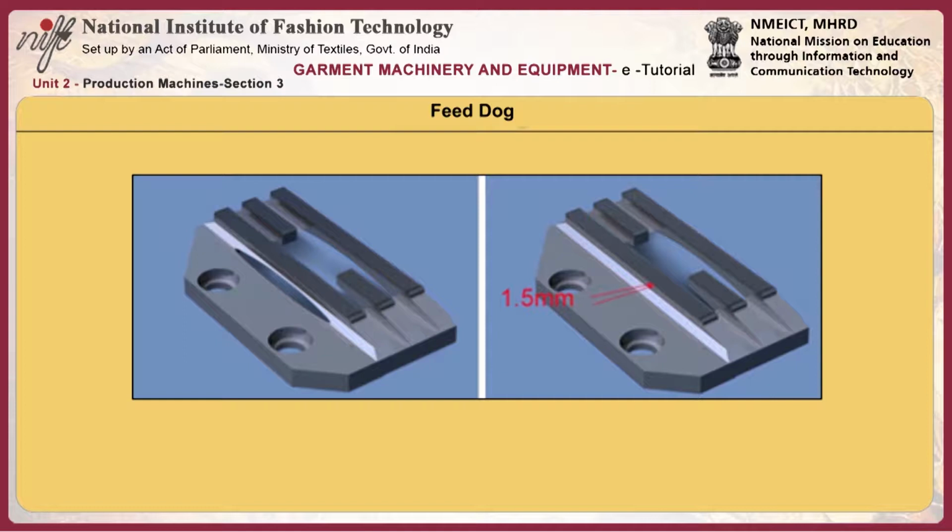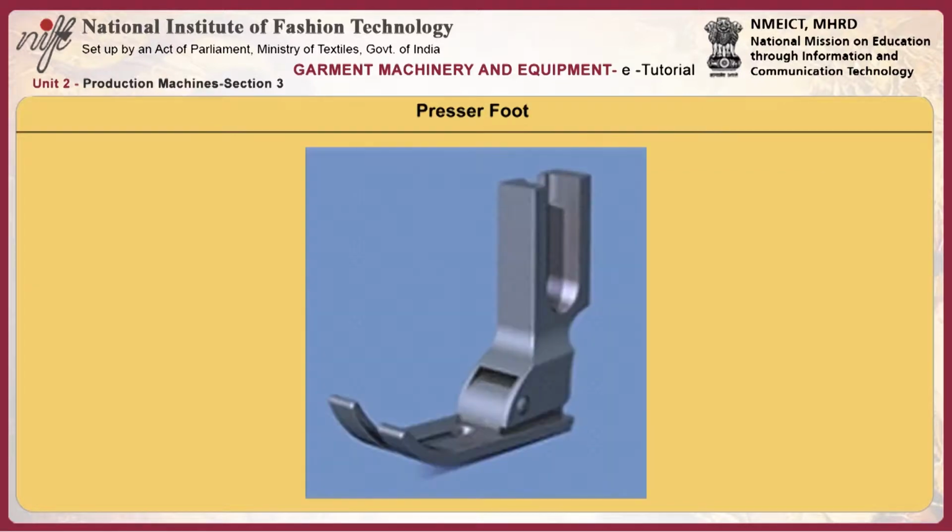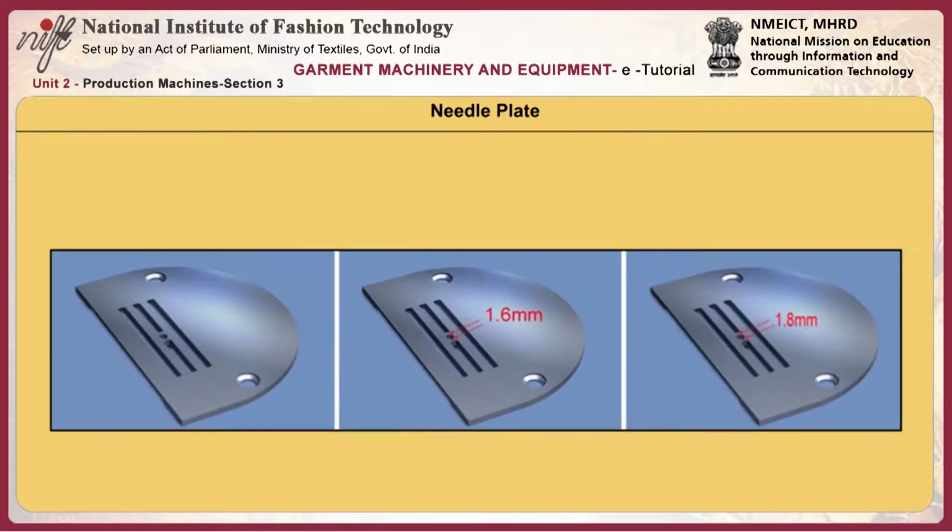The feed dog has raised lines of hardened steel, each with multiple rows of steel teeth that grip and move the material during stitching. The pressure foot is a solid or hinged flat surface that holds the material against the needle plate or lower feed during sewing. It provides stability around the needle point, which helps the correct loop formation of the stitch beneath the fabric.